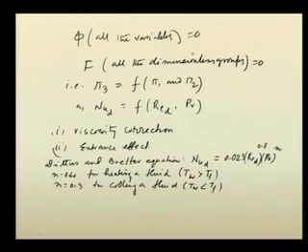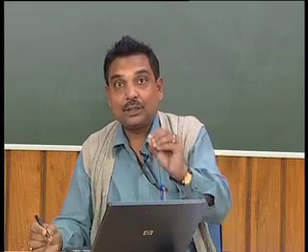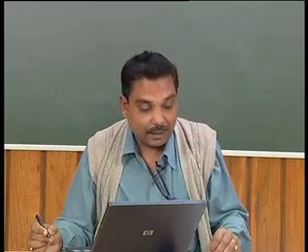This equation is applicable for certain conditions. The Dittus-Boelter equation is an empirical relationship, but we can see that it has taken care of all three fundamental dimensionless groups, which we have already shown should be fundamental for discussing this flow through a pipeline and heat transfer problem.